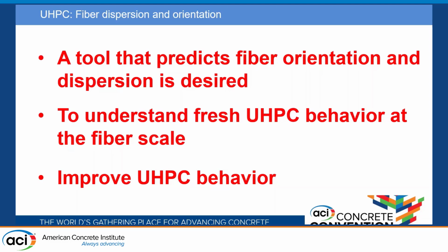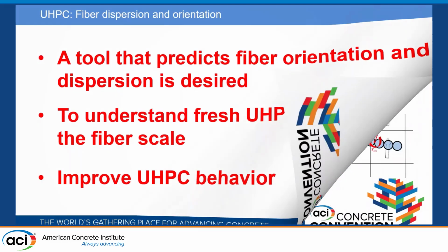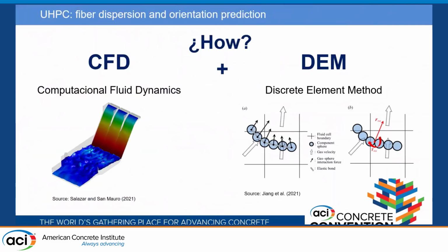We need to know what's going on at the micro scale, or at the fiber scale. So what we propose, and this is not new, is to construct a CFD-DEM model. CFD is computational fluid dynamics, and you can use it to model the movement of the fluid, in this case a non-Newtonian fluid, which is the fresh concrete. And DEM, the discrete element method, is a method to follow each fiber in a Lagrangian way.